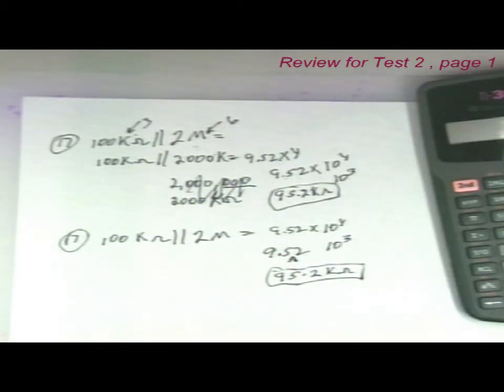Now this is a real easy one too. If you had three 22 k ohm resistors connected in parallel across a 10 volt source, power PT equals what? Now in this case you do need to know the voltage, don't you? Because we're going to figure power. And power in this case equals what? I'm listening, but you're not answering. Okay. Know your formulas. Go ahead and figure out what power equals when you're given R and you're given E. You need to write that down and maybe play this a couple of times to understand what I'm talking about.